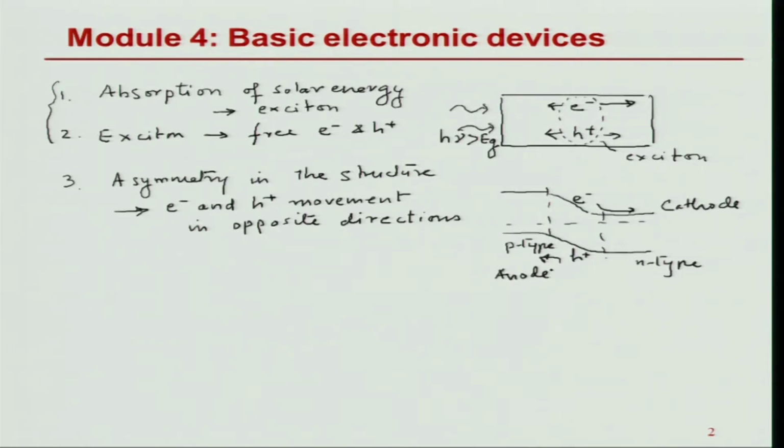So, this natural discriminating motion of the electron and holes is necessary to get the photovoltaic action. If you did not have that, then electron holes which were free will recombine with other electron and holes, and you will not get any generated voltage in the device.